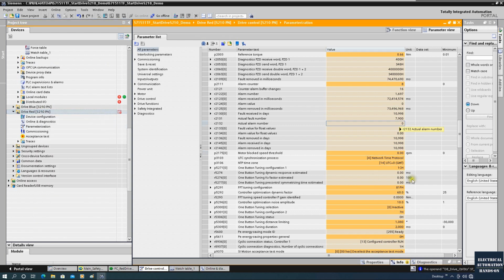Don't forget this. I will also prepare this situation while using the TorqueLimit function block. So while using the TorqueLimit function block, actually we do not need to change this parameter. Okay, so I will change this parameter online to 0. Now it is working at 0. So I will show this case temporarily first. Okay, show for the TorqueRange. Okay, now I set this to 0.